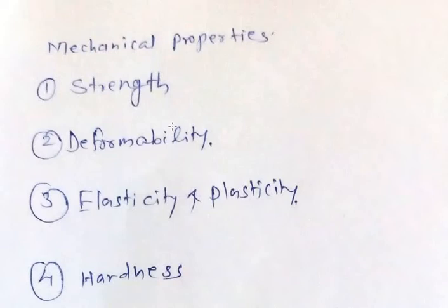In addition to the environmental conditions, rock strength depends on: size of rock specimen, type of test, duration of test, that is the rate of loading, loading condition, cycle of loading, confining pressure, degree of saturation, and physical characteristics of rock material.